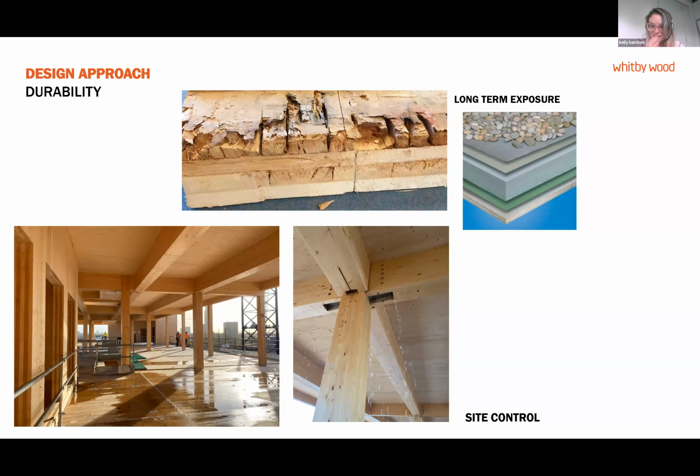So you need to make sure that your connections are really well detailed, really well thought through, and on your site inspections, if you see something like this, make sure there's extra measures in place that has then been tested with a moisture sensor afterwards, to make sure it's hoovered out. You can get little vacuums in there to get the water out afterwards, tested, and then plugged up and sealed so that it can't get back in there later. And everything from the top should be a little bit more sealed up so the water can't get in there in future.